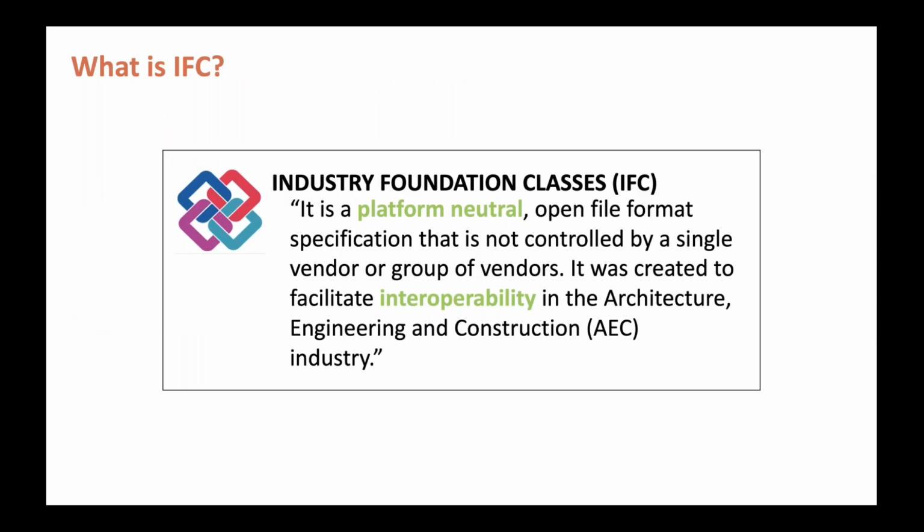I would describe it as having a chocolate bar and removing the wrapper from it. And you still have the chocolate bar. So all the data, all the information, all the geometry gets transferred to the IFC, but none of the vendor specific, like none of the Revit or ArchiCAD or Tekla kind of goop. That's all left behind, and the data gets structured in a format that's easier for everyone to understand. At a very high level, I think of the IFC file as the PDF of BIM. It takes a file, simplifies it to its essentials, allowing for more collaboration outside of the native software.